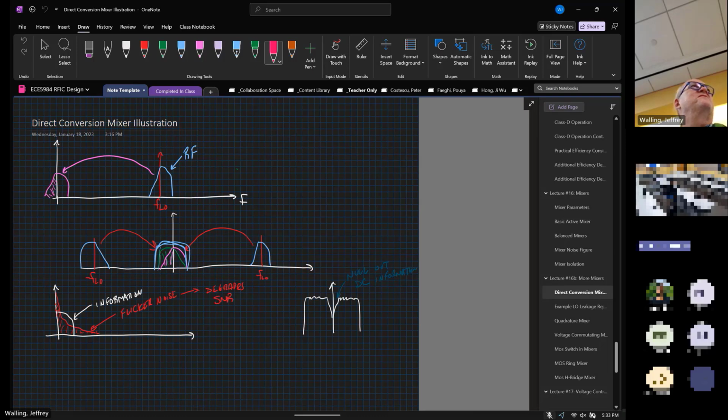There's a fundamental transformation, and it was that with digital signal processing, we could start doing things like nulling out the information that was right around DC, so you don't send information right around DC, and that means if there's flicker noise there, we're not putting that noise directly on top of usable signal. So most modern signals do something like this. They'll null out the carriers that are right around DC, and we don't send information there.